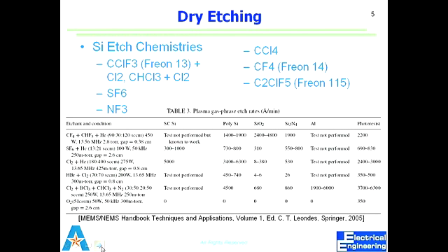If I have silicon dioxide used as mask and I want to etch single crystalline silicon, which recipe will I use? Chlorine and helium, right? The third one. Why? Because the silicon etches 10 times faster than silicon dioxide. What does that tell me?